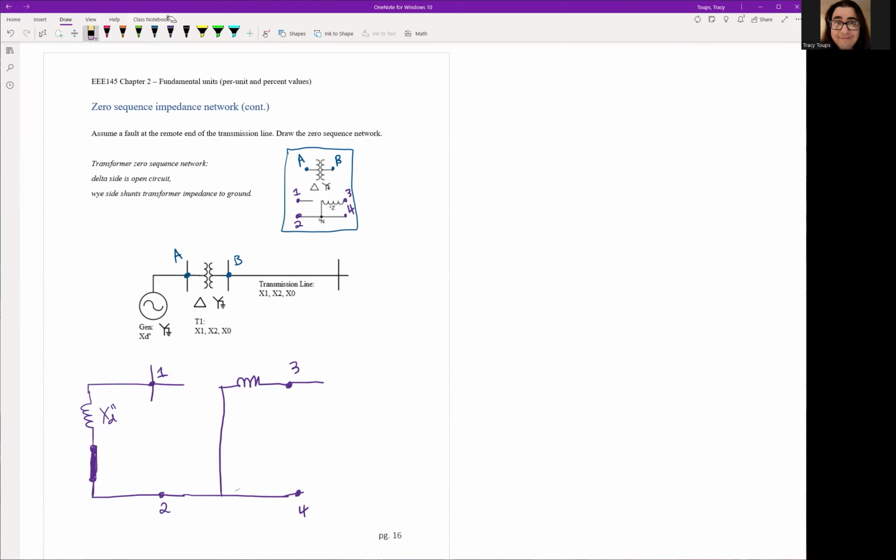3, we left the transformer, we hit bus B. So let's move that 3 over and let's put the bus in its proper place like that. There you go. Okay. And just across, remember, this is bus A, this is bus B. Okay. So we really took A and B and we swapped over 1, 2, 3, 4 points and we just put in that network right there. Okay. Now this impedance right here is a transformer impedance. This is going to be our X0T. And now that the 1, 2, 3, 4 box is put in, we're going to keep on going with the rest of our network.